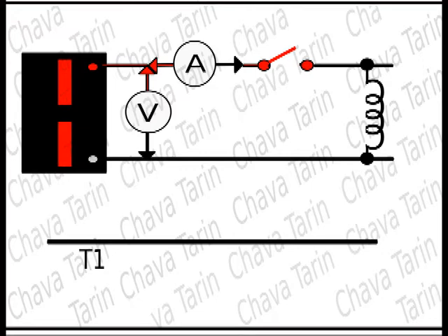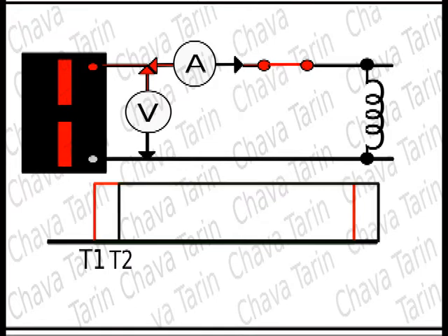An inductive load is kind of odd. When turning on the switch and applying the voltage, the coil at first opposes the current flow, and after a fraction of a second the current flows freely. On the other hand, if we now turn the switch off, the inductive load tries to keep the current going, and even a spark jumps between the contacts of the switch.